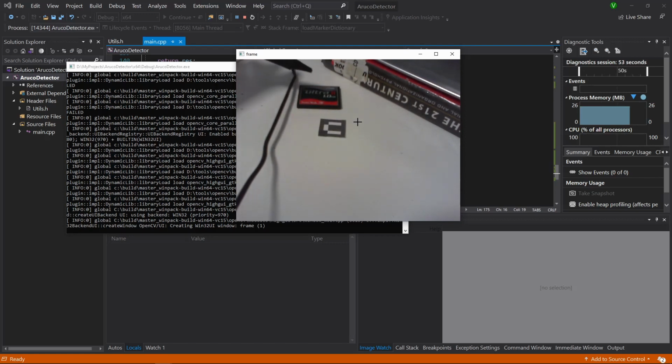It doesn't matter if it's a real marker or not, we can calculate some signature for the detected square, and then we compare this signature to a list of predefined signatures that we know are valid for our marker, and if we have a match, we found the marker.